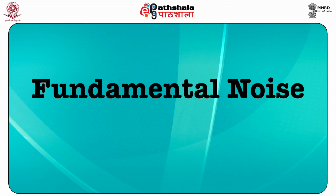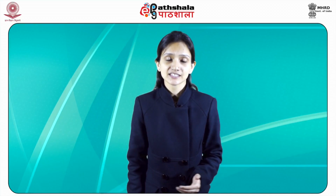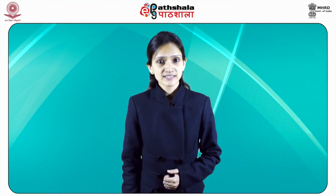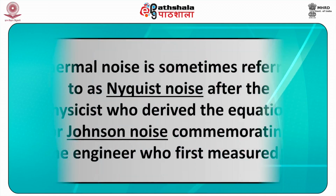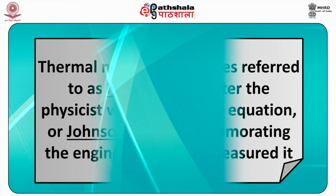First, fundamental noise. Thermal noise. Noise that originates from the thermally induced motions of charge carriers is known as thermal noise. It exists even in the absence of current flow. Since thermal noise is independent of the absolute values of frequencies, it is also known as white noise. Thermal noise is sometimes referred to as Nyquist noise, after the physicist who derived the equation, or Johnson noise, commemorating the engineer who first measured it.